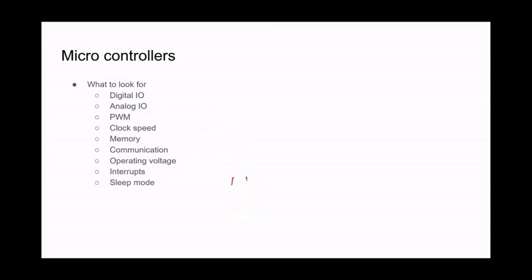The next is operating voltage. This one is really important because sometimes you don't want to have a big honking battery on your board if you don't need that. That's one of the reasons why we like the ATtiny85, as opposed to the Arduino, which needs a minimum of 5 volts typically. 5 volts up to, I think you could power it up to like 17 volts, although it's not great, right? You're using a linear voltage regulator, so 12 is better. The ATtiny can go as low as, I think it's 1.8. I might be wrong there. And a max of 5.5.